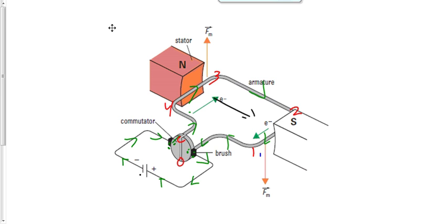So whatever section of the wire is on the left-hand side will always experience a force upwards, except when it's oriented like this. It just keeps going, though, when it's oriented like that because of inertia. And this side will always experience a force downwards. What's the net result of that? A force, inertia, a force, inertia, a force, inertia, and so on. What ends up happening to this thing? It spins around, right? That's the armature, what's connected to the drill bit.